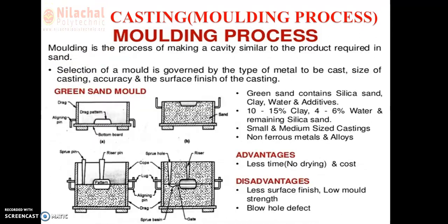So in the previous slide also, here you can see this is the prepared mold. To prepare this type of mold, we are using the pattern here. We are separating the cope side and this one is your drag side. By a separate method we prepare the cope side and the drag side, and by combining them together we complete the mold preparation.